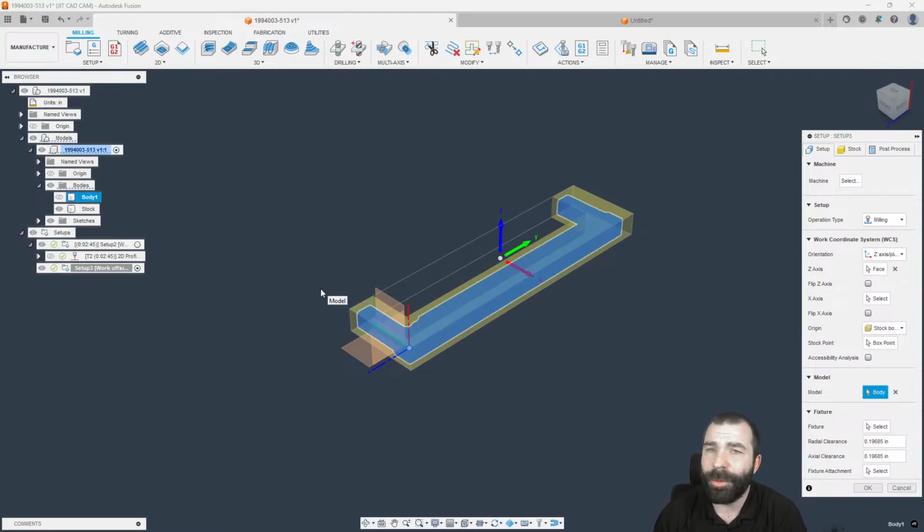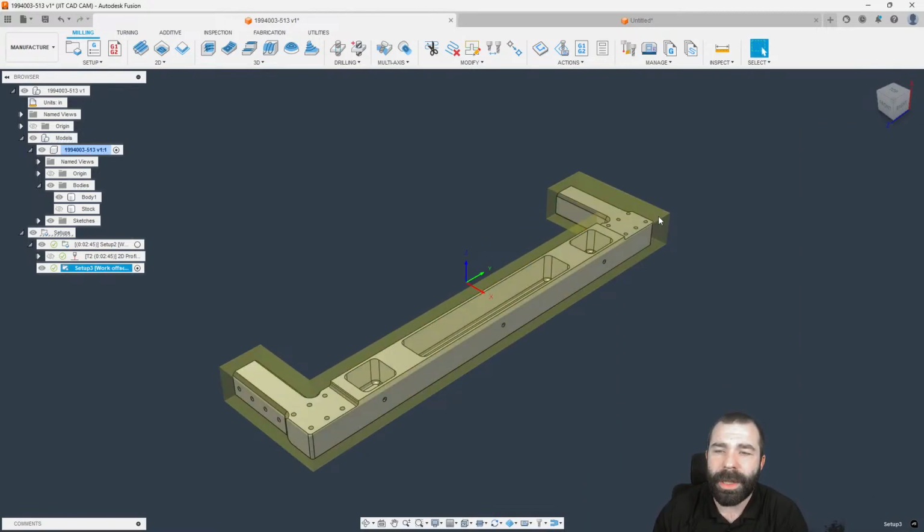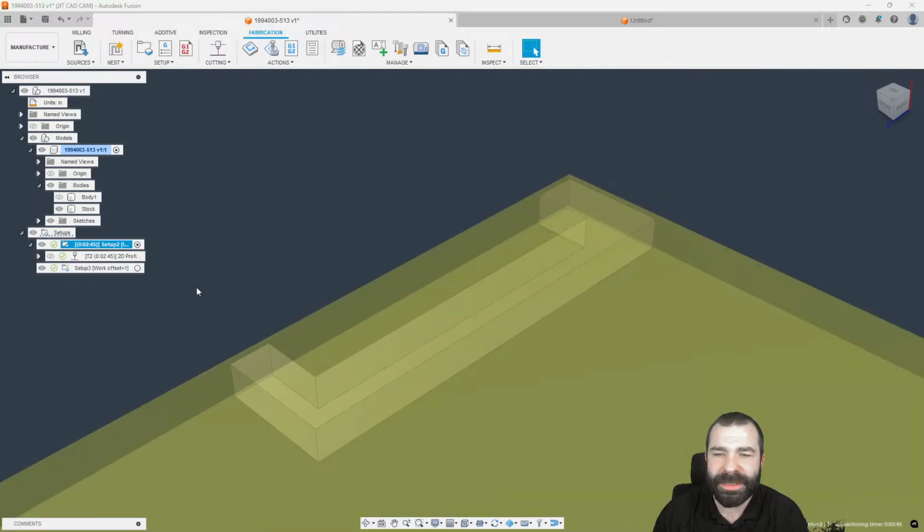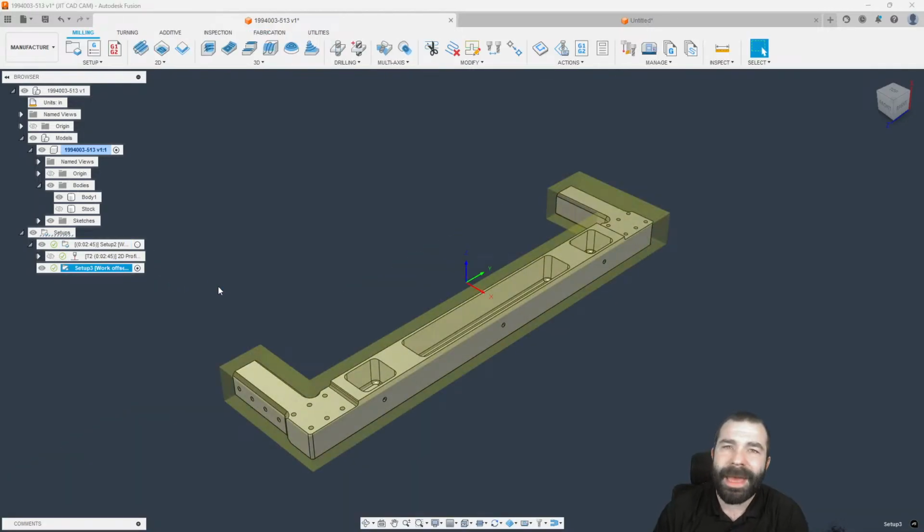And there it is. Now, what you guys are seeing me do in the design tree, there's a reason for it. And you're going to see why here in a minute. Because I actually have my synchronizations turned on. So when I hit OK, notice how one, it got rid of my solid body but kept the setup stock. And then two, it turned on my other body. So if I'm jumping between setups, notice how I can automatically set this up to present itself so that I can see whatever it is I'm latest and greatest working on. And how you do so is down here at the bottom under synchronize. I tell everybody check all three of these so that you can jump from one to the other quickly and see that turned on.